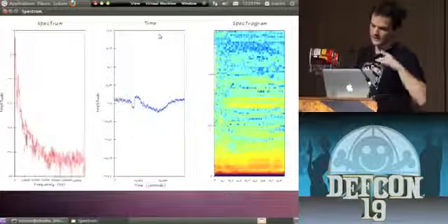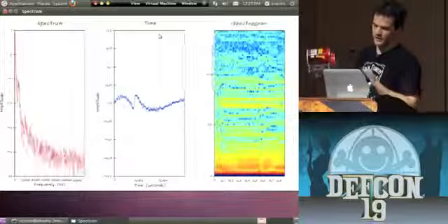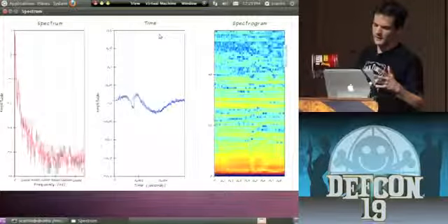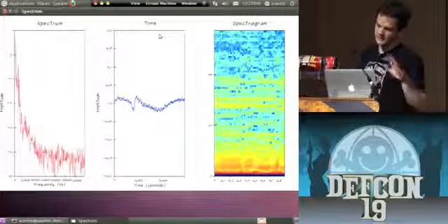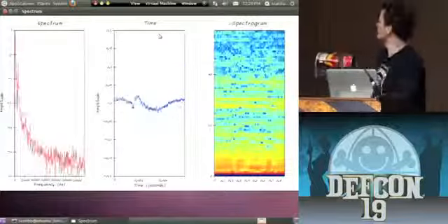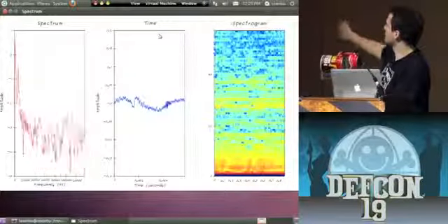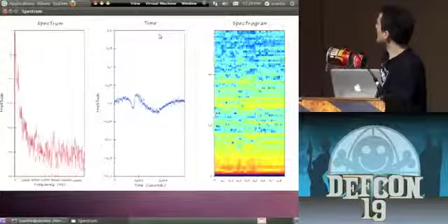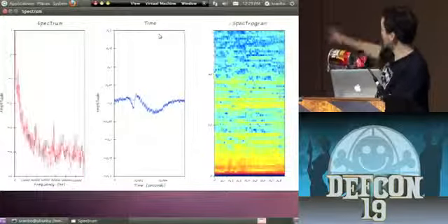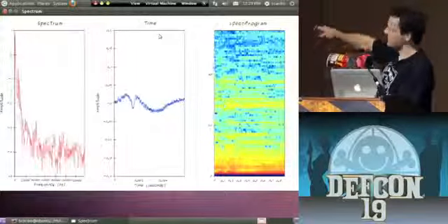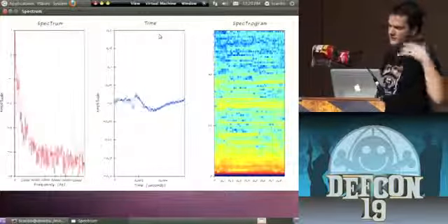So this is literally at low frequency. It's basically an audio tone is what it would sound like, and that's related to the signal. It's not very directly related. So what we do is we Fourier transform that, which you can see on the left and the right. The one on the right is kind of a scrolling view of that. It's kind of hard to see the scale, but on that spectrogram view, those numbers are supposed to be the distance in meters to whatever you're looking at.